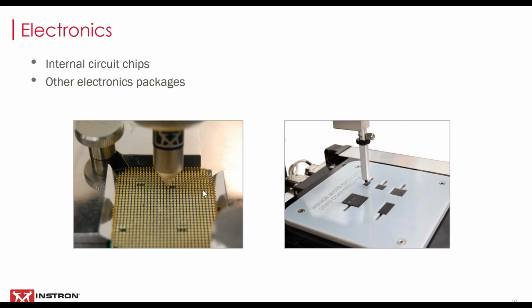It's not only the end product that needs testing, the internal components of the device need to be tested as well to ensure that they can handle possible loads they'll be subjected to. When the end product is bent or twisted, or when it gets bounced around during storage or transportation, there's always that risk that the internal components could loosen or become damaged. So those need to be tested as well.